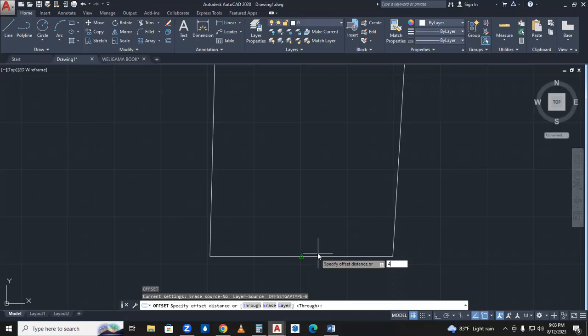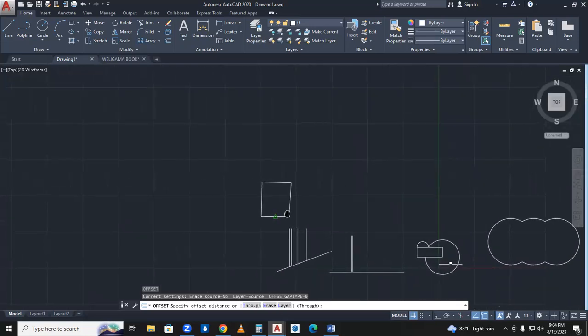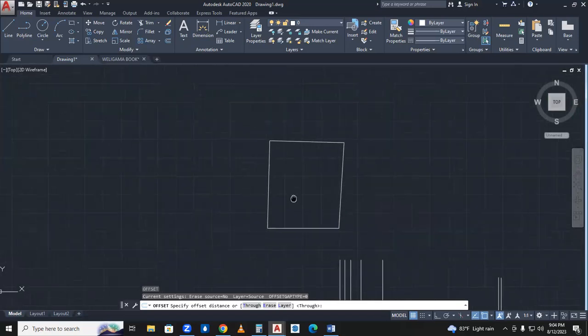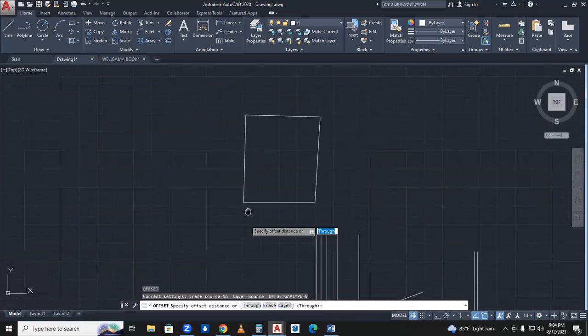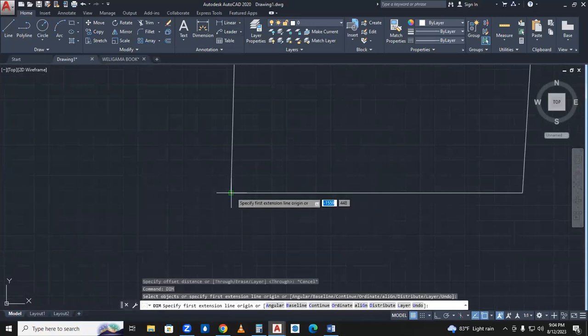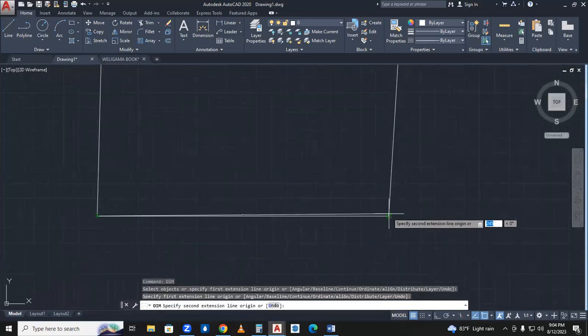We are talking about a 4 inch block, but what units are we drawing in? Inches or millimeters? Millimeters. So we have to convert it. 25 millimeters is equal to 1 inch, so we put 100. But we don't know the scale we have drawn, the lengths. So initially we'll measure how many millimeters this is. If we just give offset, it will be something else.